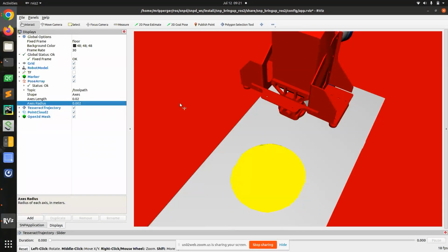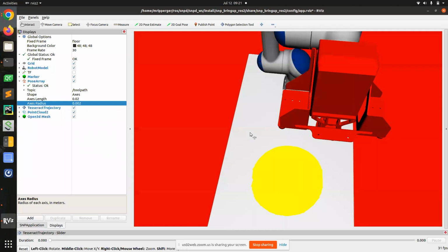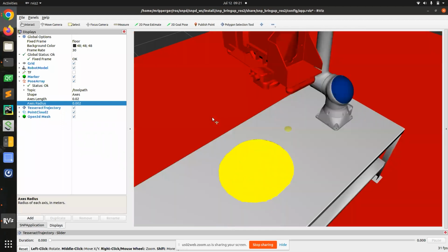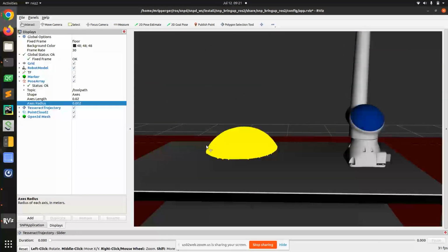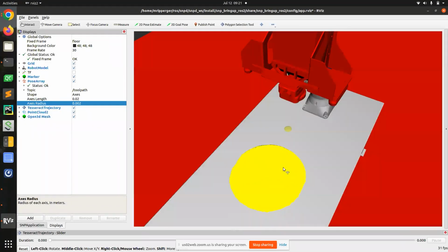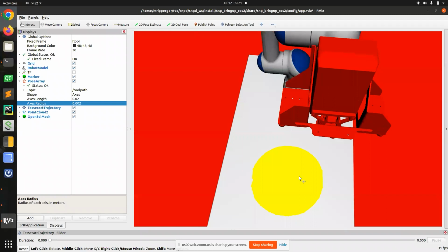So yeah, this is cool, but maybe we don't want to do toolpath planning over the entirety of the surface. In our case, actually, it's hard for the robot to get down towards this back end here. So we want to be able to select some region of interest on this particular mesh. So we built in this region of interest mesh modifier.